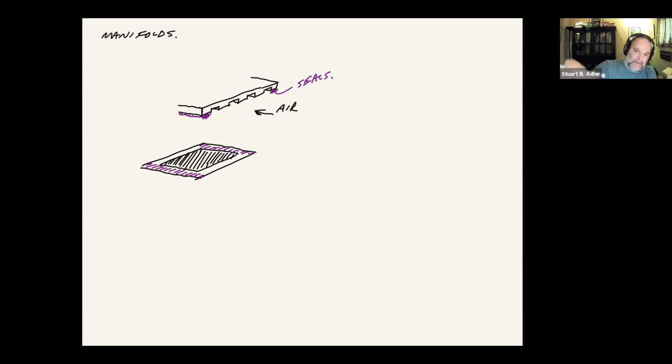So the air is going to be blowing through here, past the cell, and we're going to lead it along that path with these flow channels. The basic purpose of the flow channels is to allow enough volume for the air to flow without too much pressure drop. The reason it isn't just one big flow channel is we need to get current through it. That's the purpose of these additional features that are sticking out. We're making electrical contact everywhere along the electrode by virtue of these features that stick out.